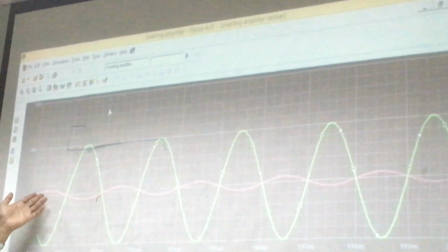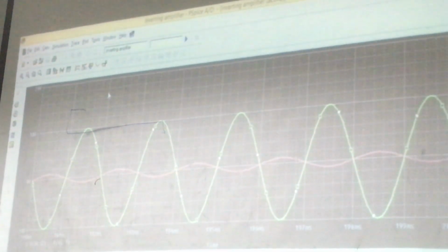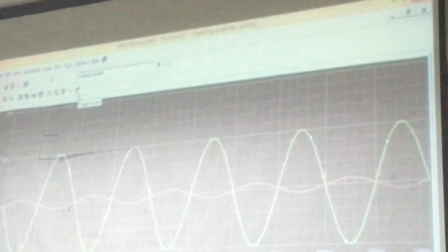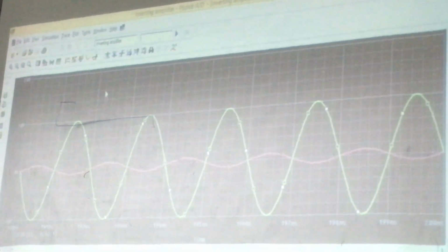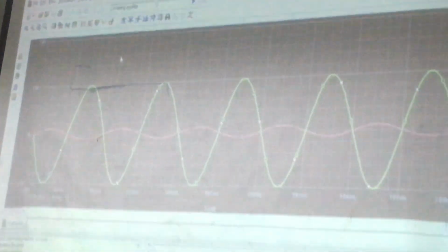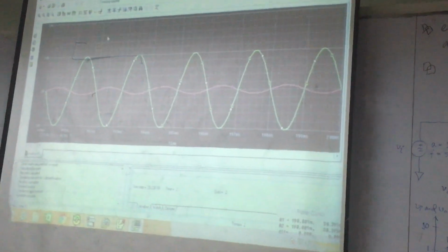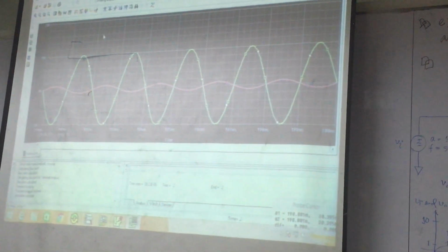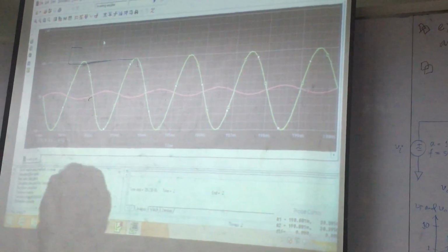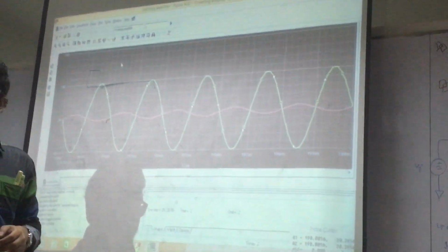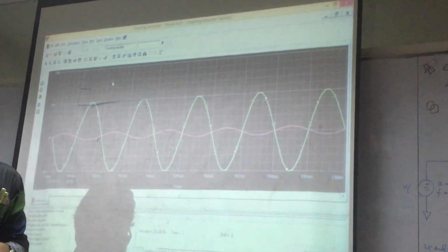Now how do you select that? Using cursor functions. So let's bring in the cursor, which is this guy. Toggle cursor. You click that. Once you click it, you get 2 cursors. One horizontal, one vertical. A line is going to make up a cursor. So you got 2 of them. One works with the left click, another works with the right click. So left cursor, right cursor, you keep that in mind.